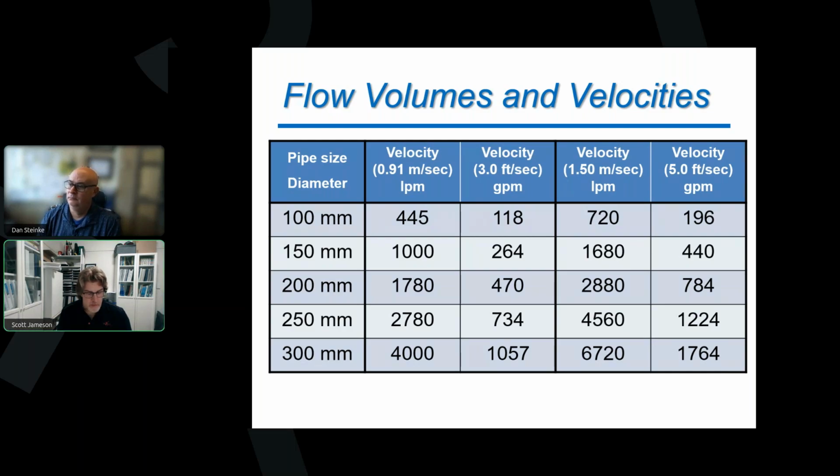Yeah, so if you've got residences hooked up at the top there that have that low pressure, you're going to have some issues there. If it was me doing it, I would locate their service lines and shut their service lines off while I was doing the flushing. That would give me some sense of protection that I'm not going to be siphoning the water out of those homes.